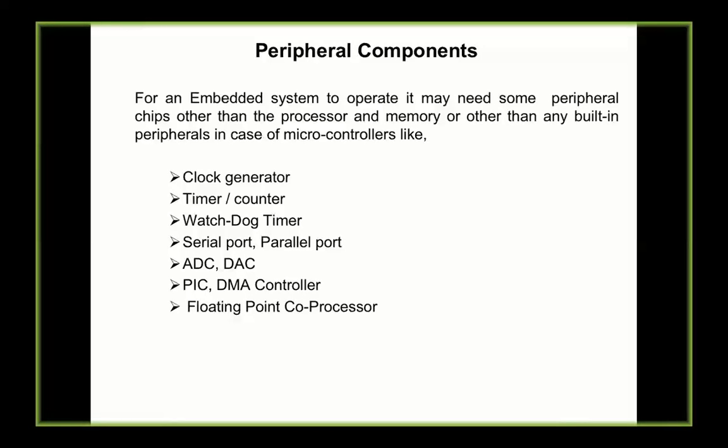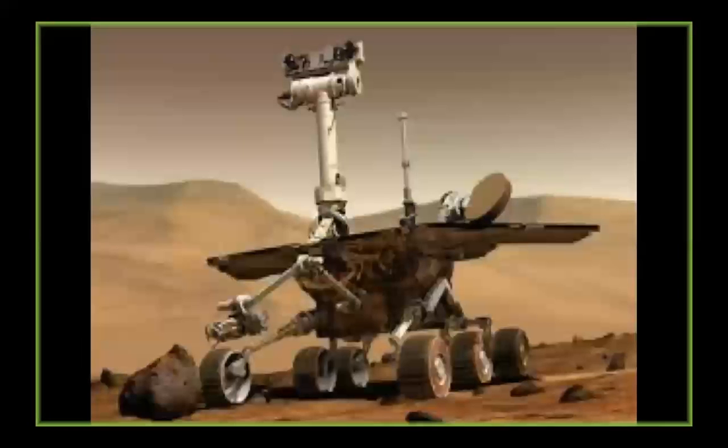So watchdog timer usage, and the way you communicate, like ports, serial port like RS-232. You should know how your baud rates will be set, which UART it is, 16550, 16C550, or how a TTL layer helps you to be compatible with your PC communications, or TTL, transistor-transistor logic, and your voltage level transitions should be known to you. You should know how to support baud rates and so on, guys. Again, a lot of example products, I'm just going to skip them.